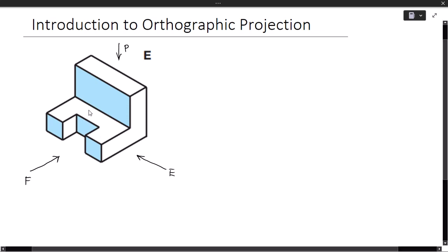In third angle projection, we get the opposite direction of the front. The front is pointing towards the right, this arrow here. So if it's pointing in the right, we're going to get the opposite direction. Our front is going to be in the left. And now we position it in this part. You'll see why very soon. Then our end is going to be on the right part of our front.